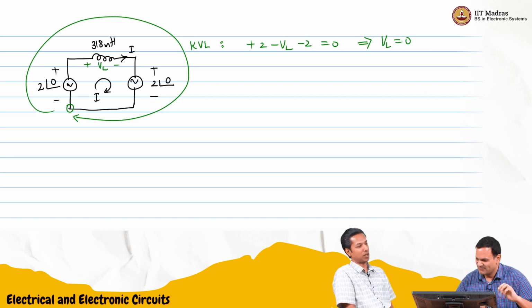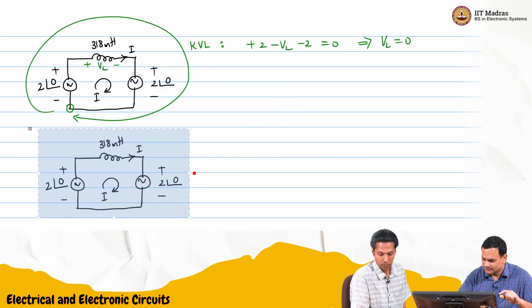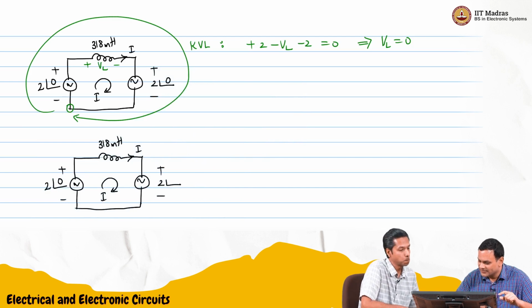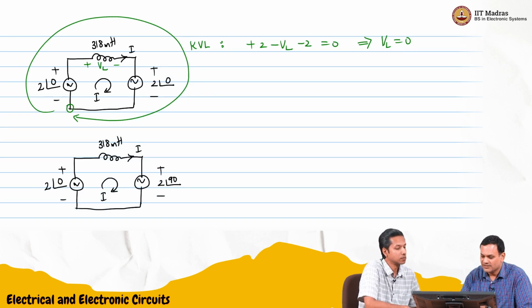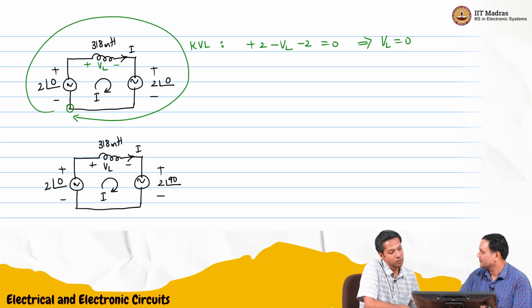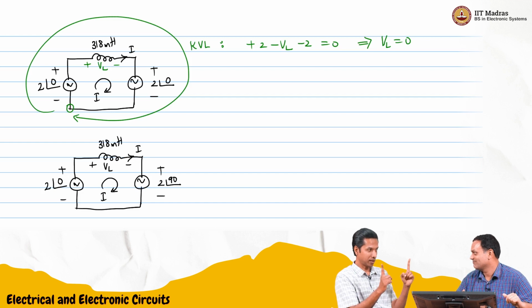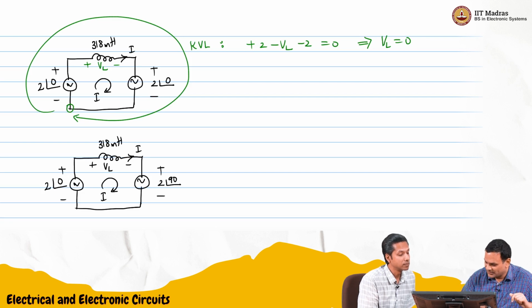So we'll make some angle for one of the voltages. Okay, I'll change this. Shall we make it 90 degrees? 2 angle 90? Okay. Which means this was 2 sin omega t, this would have been 2 cos omega t. It would have been leading the sinusoid by 90 degrees. So this definitely is going to give us a non-zero voltage, because there is a phase difference, although the magnitudes of the voltages are the same.